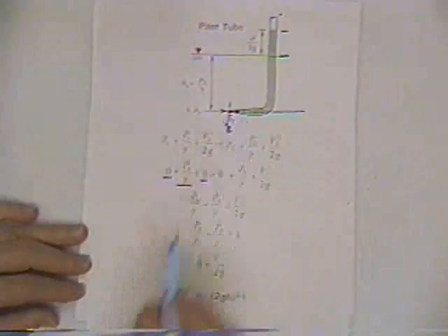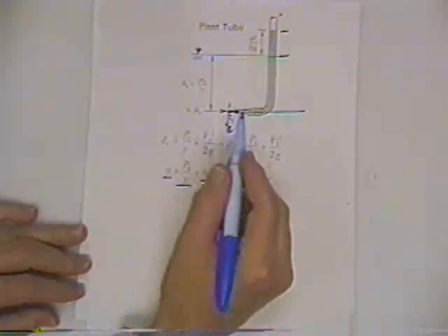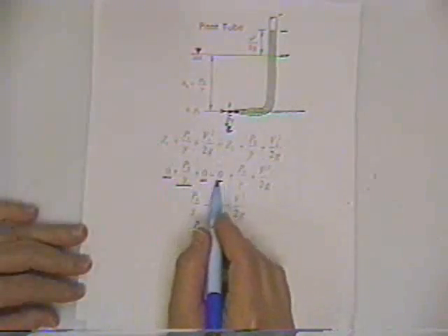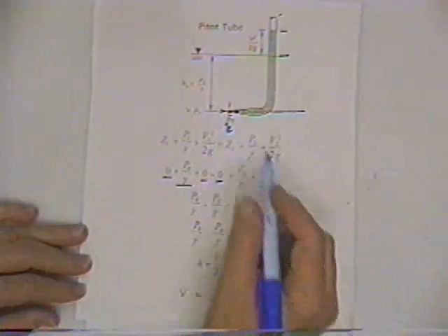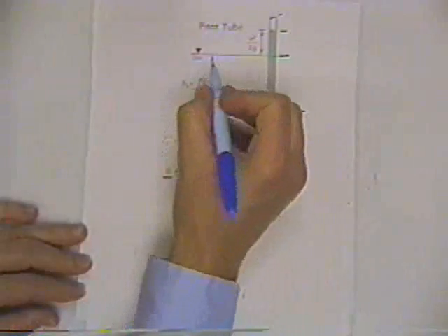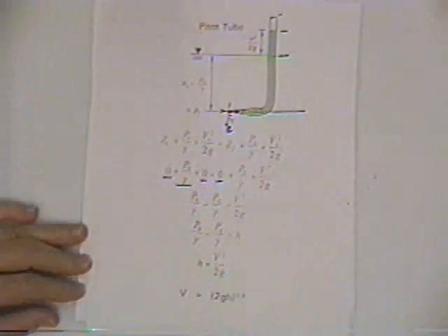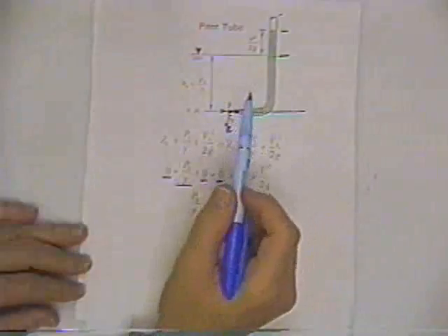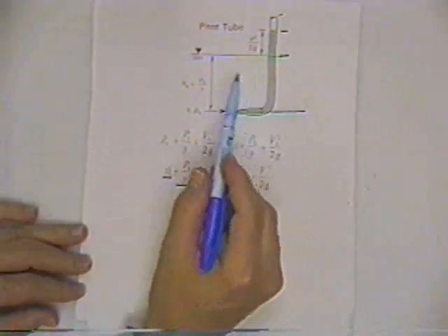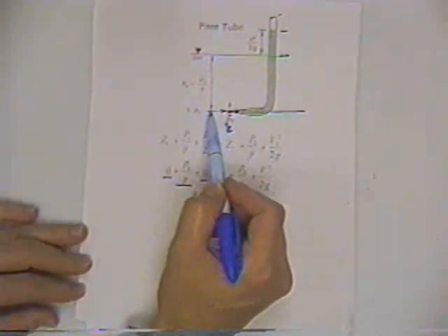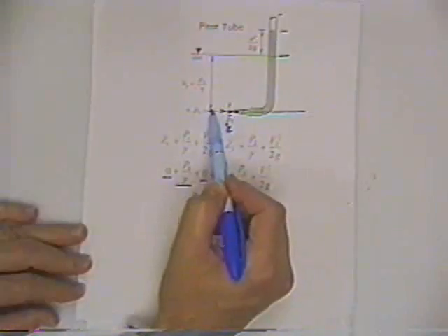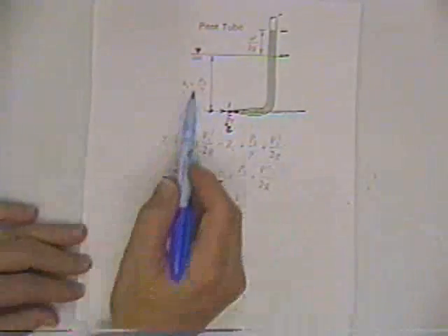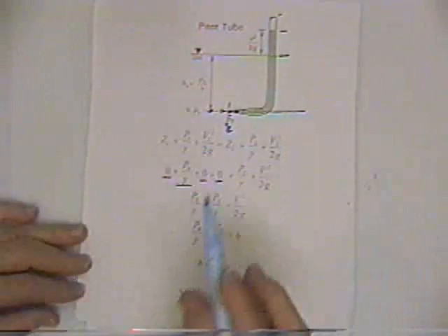Now, if you're outside the entrance to the tube, and say we're at the same vertical elevation, so our Z is still 0, and we've got some pressure, and this is the pressure head. Outside the tube, the pressure head is no different than from fluid statics: the pressure would be gamma times the vertical difference in elevation between the water surface down to this point of interest out here in front of the pitot tube, and so that's just the pressure divided by gamma.